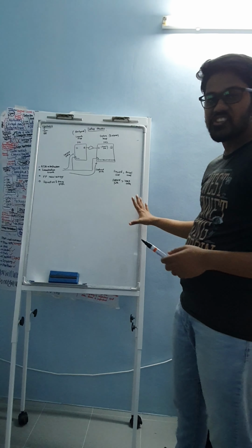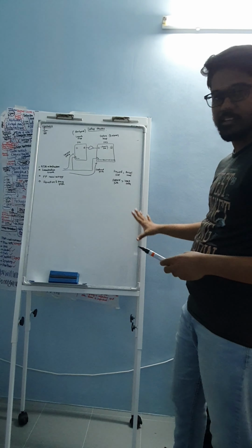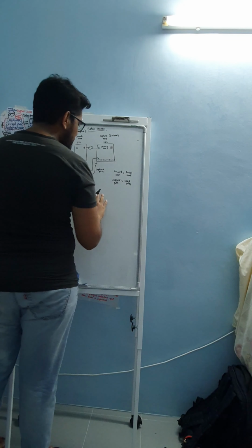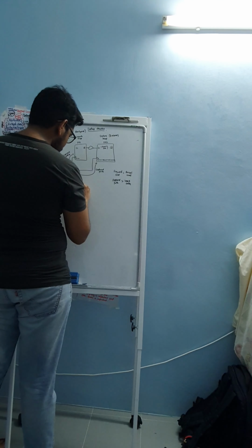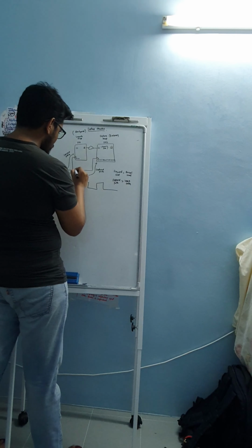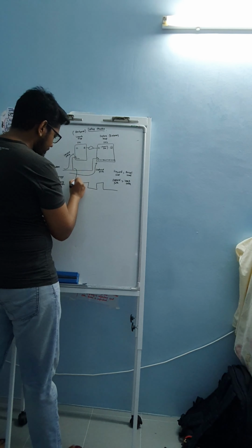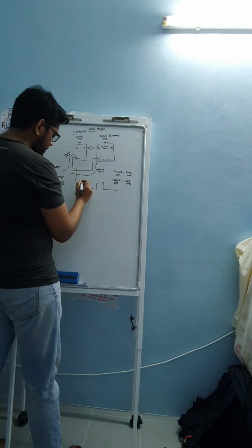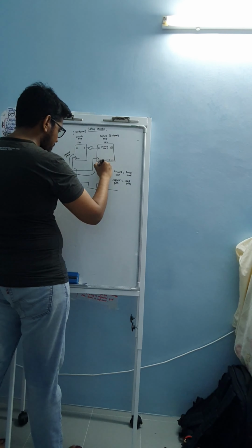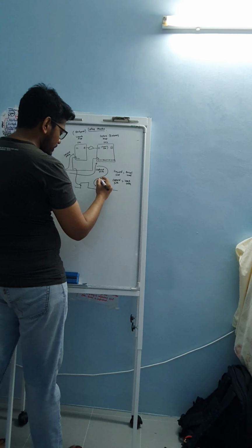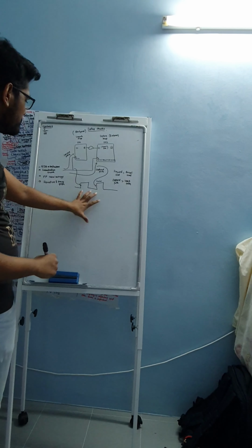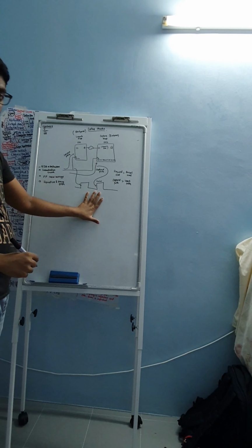Otherwise, you're going to see a setup violation here. Once again, this is highly dependent on the clock frequency. That's the reason you will be seeing your launch path over here triggered at the first cycle, and then your capture path will be checked over here. This is your T setup. So you will be seeing your path right over here.